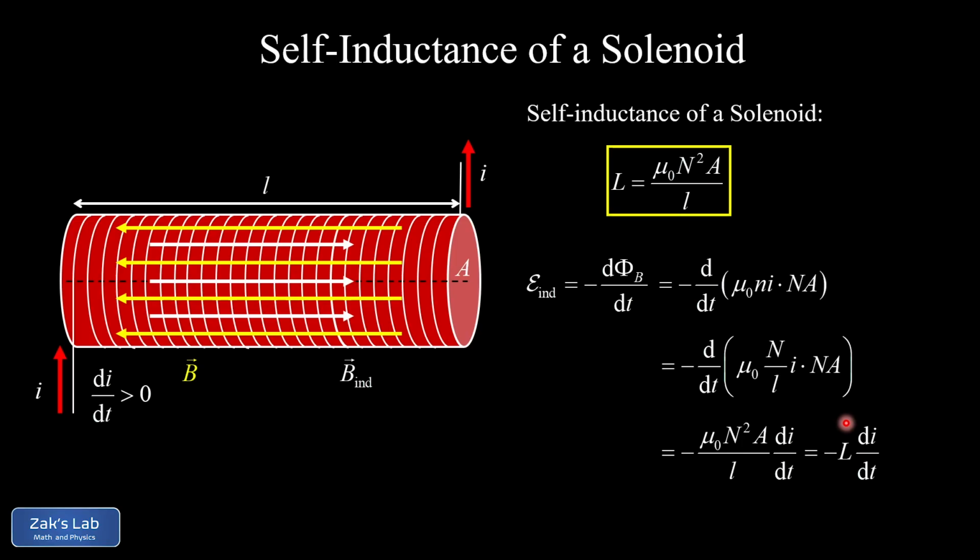The inductance of a coil can be thought of intuitively as how strongly that coil will resist changes in current. For the same rate of change in current, a larger L means a bigger induced EMF fighting that change. This allows us to think of inductors as the source of a kind of current momentum in an electric circuit, and we'll see that behavior in the inductor-resistor DC circuit as well as within a variety of AC circuits.